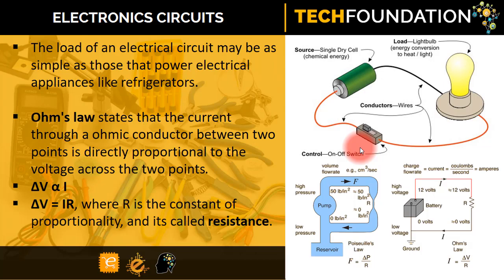Please do not confuse voltage drop across a conductor with EMF of the circuit itself. In future videos, I will explain why. So from Ohm's law, we can write that a change in voltage is directly proportional to the amount of current flowing through the conductor. That is, change in V is proportional to I. The constant of proportionality here, as mathematics demands, is the resistance of the material, and again, do not confuse resistance with resistivity. However, Ohm's law has a limitation, which is temperature.